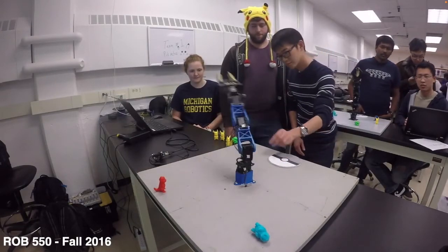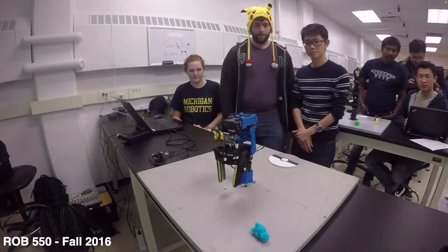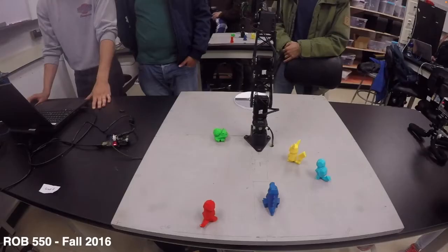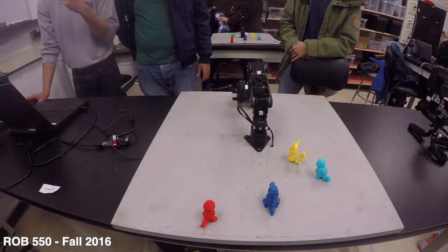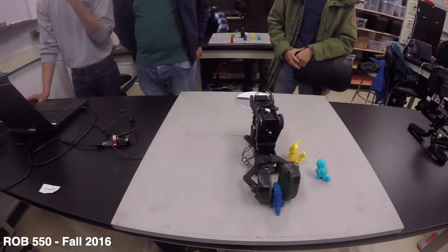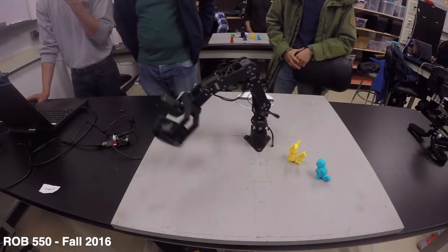What would be specified is that the robot would have some visual detection of where within space the Pokemon objects were located. The robot then would have a set point defined for where the end effector should pick up the objects in world coordinate frame. And using that desired end effector position, the robot could know, using inverse kinematics, what joint configuration would be needed in order for the end effector to be at the correct pickup location. At that point, it could plan a trajectory for the pickup location using some additional techniques. And then once again, it could define a place location at what is shaped like a Pokeball, and that circular place location would give it a desired place location in world coordinate frame, which once again, using inverse kinematics, it could solve for the proper joint angles to execute the place action.